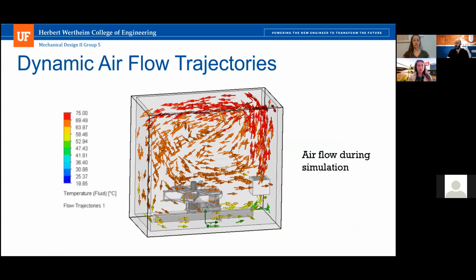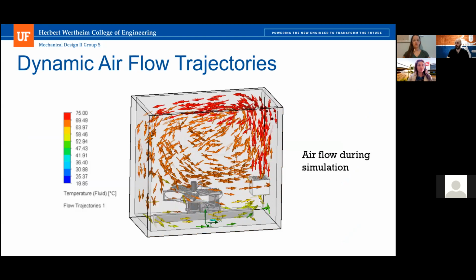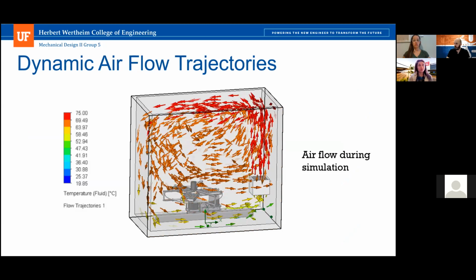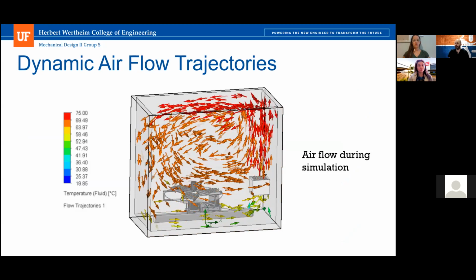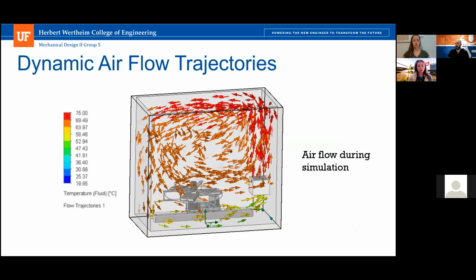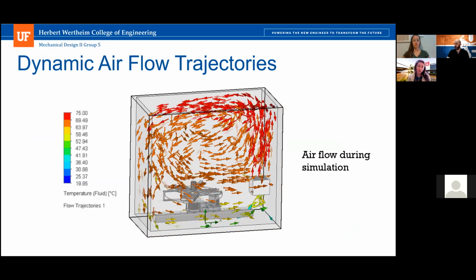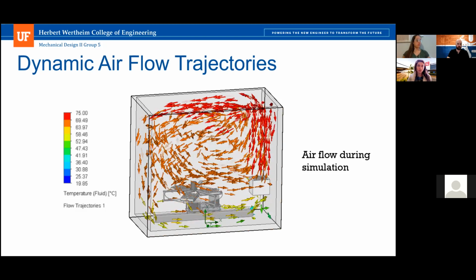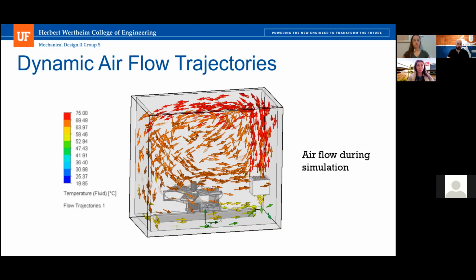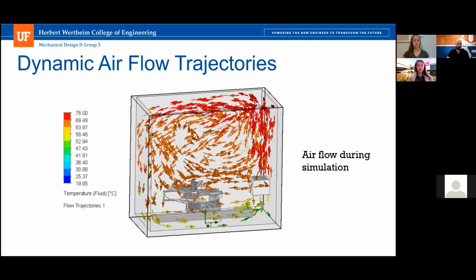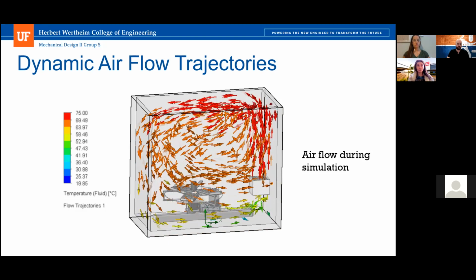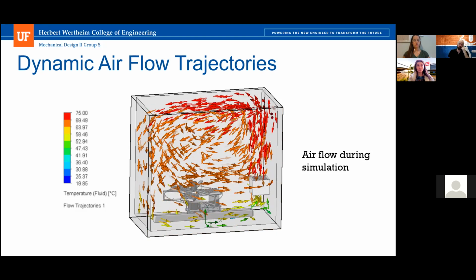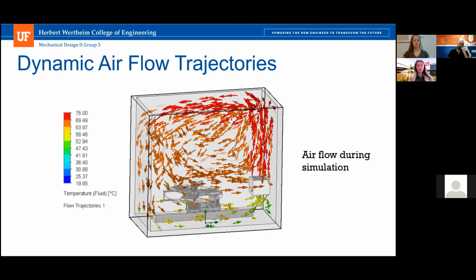Now, to determine the orientation and the placement of our heater, we conducted a flow simulation to see how air flows within our chamber at different heights, in order to ensure that we set it at a reasonable height within the chamber so that all the cool air can be properly sucked in. We determined a range of between 75 to 125 millimeters higher from the inside chamber floor, which should be sufficient to heat the system. Next slide.